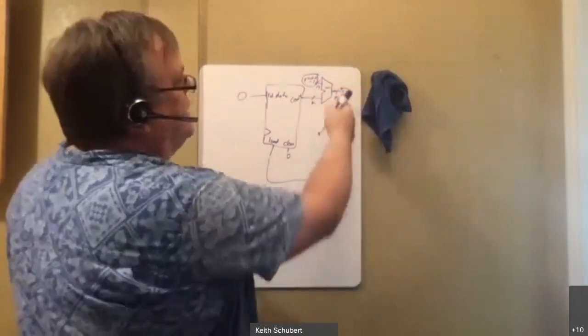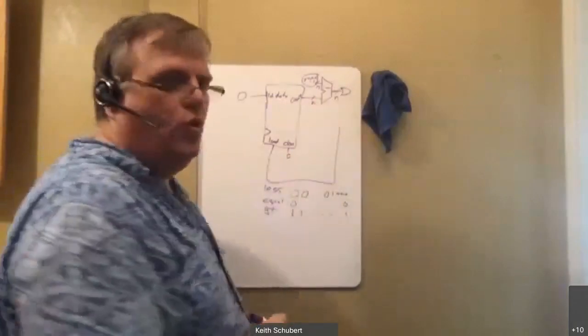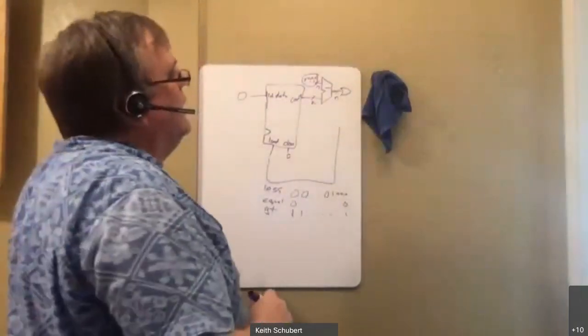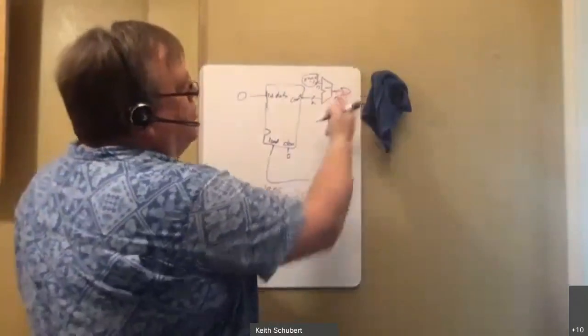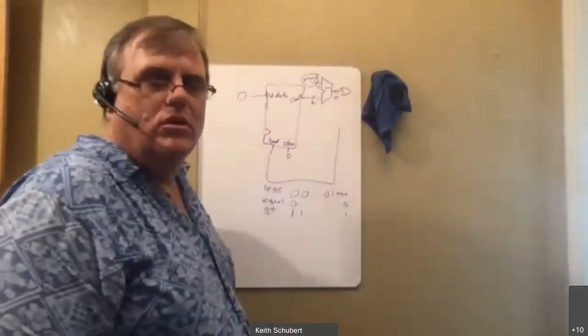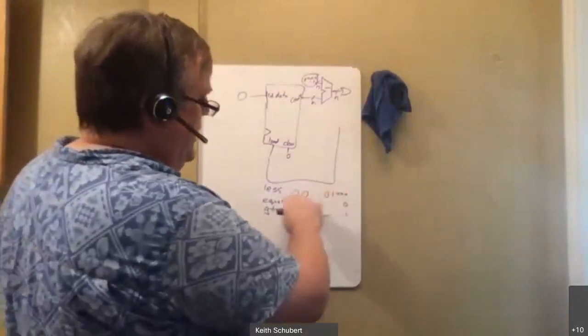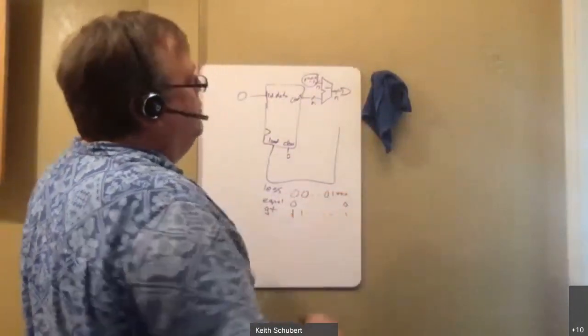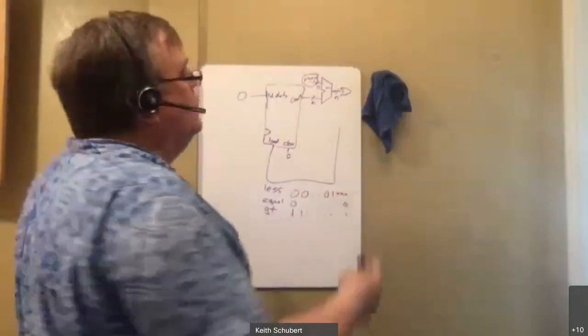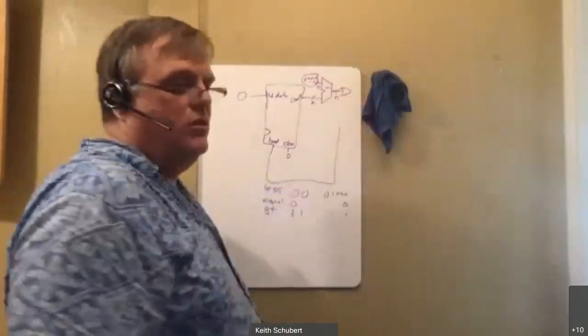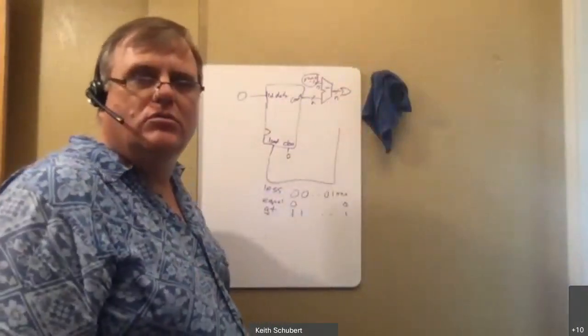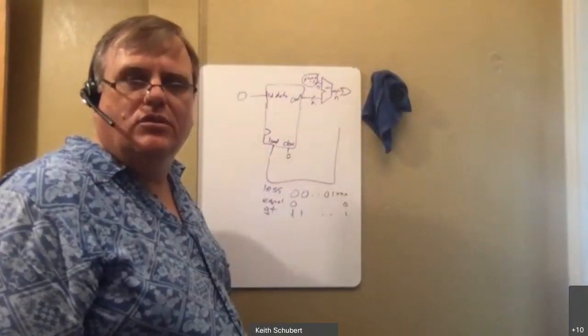And what this means is I take all n bits and run them into the OR. Now, if all of these bits are 0, then I'll get a 0. In any other case, whether it's less or it's greater, there'll be some ones, which means the output of this will be ones. Does that make sense?